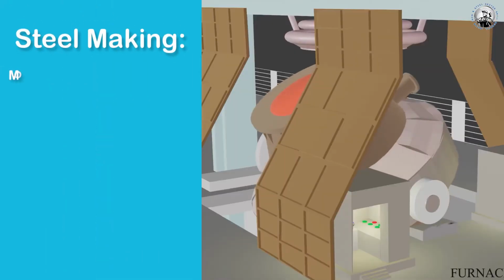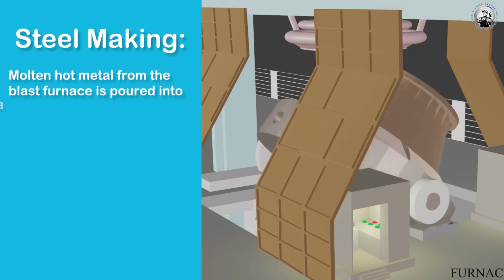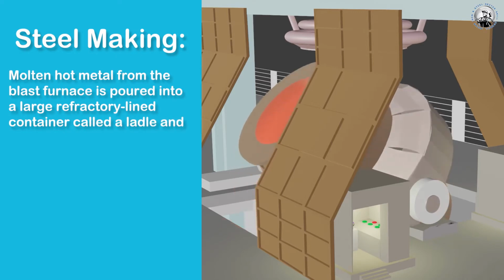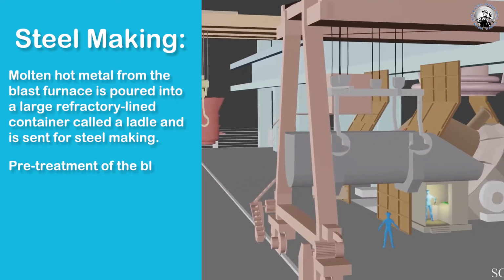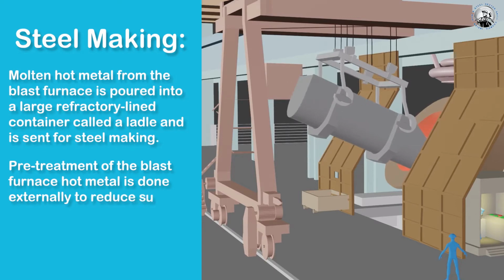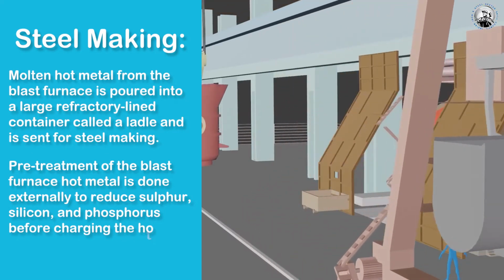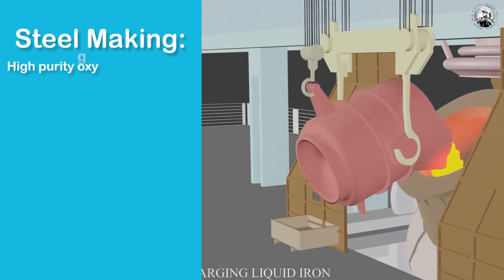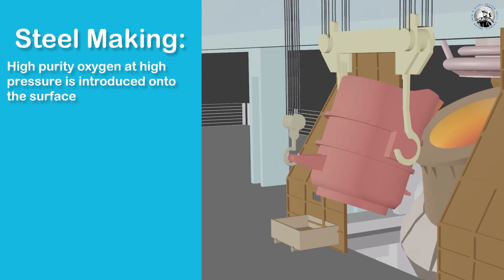Steel making. Molten hot metal from the blast furnace is poured into a large refractory lined container called a ladle and is sent for steel making. Pre-treatment of the blast furnace hot metal is done externally to reduce sulfur, silicon and phosphorus before charging the hot metal into the converter. High purity oxygen at high pressure is introduced onto the surface of the iron bath through a water cooled lance.